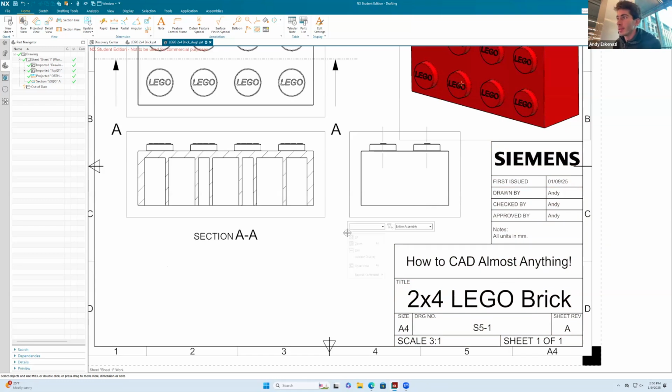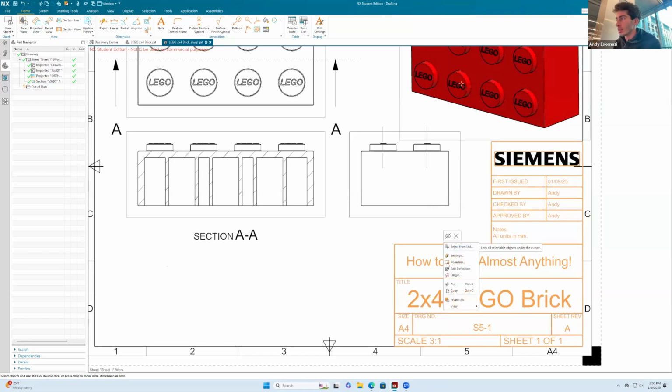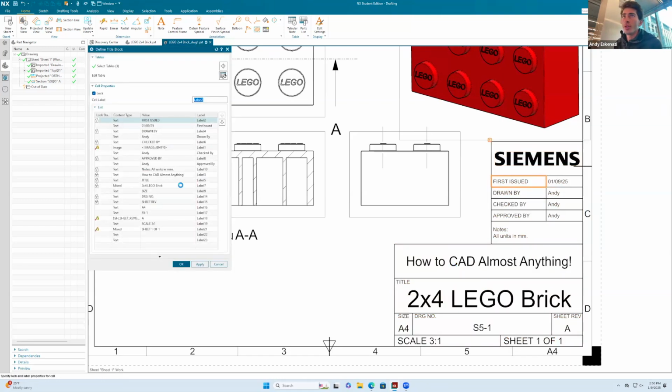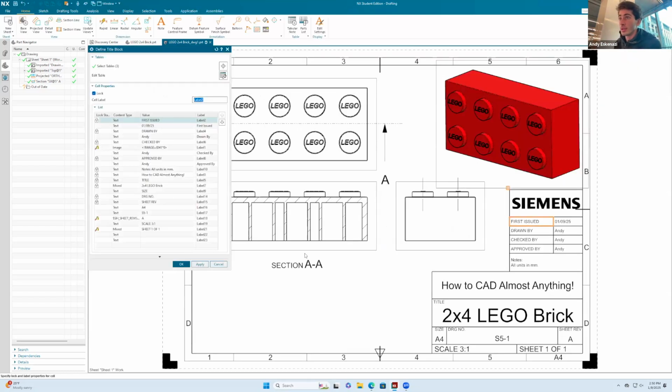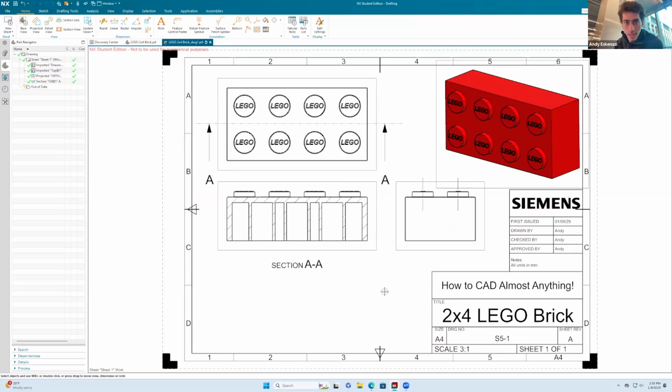If you do want to edit the table, what you will need to do is here, go to edit definition, and then just click in there where it says edit table, and that allows you to go back here. And then once you're done, right click and choose finish edit table. Because if you exit, I believe it just loses all of the changes that you had already employed, which is what we did. Then click OK, just in case.